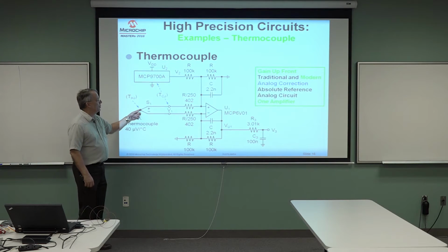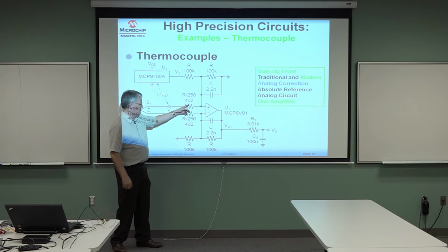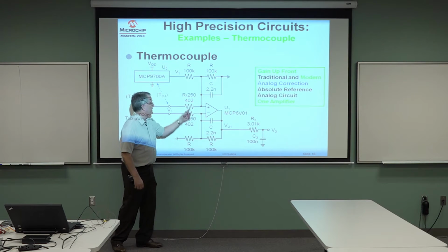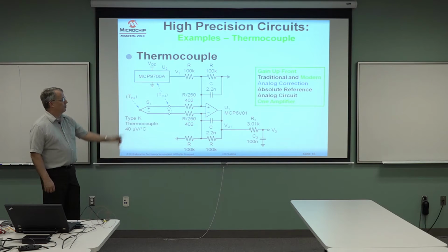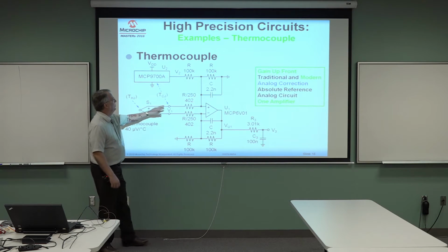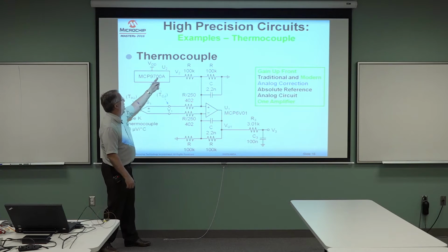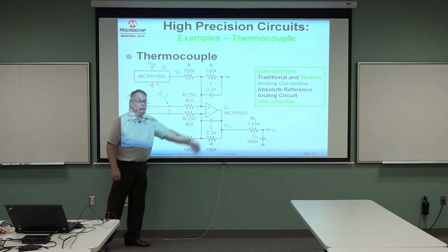This thermocouple does not have great sensitivity, so we need a lot of gain. So its gain is 400, that's about a gain of 25, or 250, I'm sorry, about a gain of 250. And we filter it at the output. So this is a way of summing this voltage and this correction voltage that is due to this temperature and getting the corrected output there.